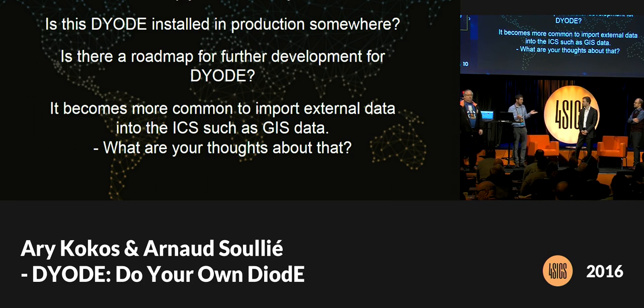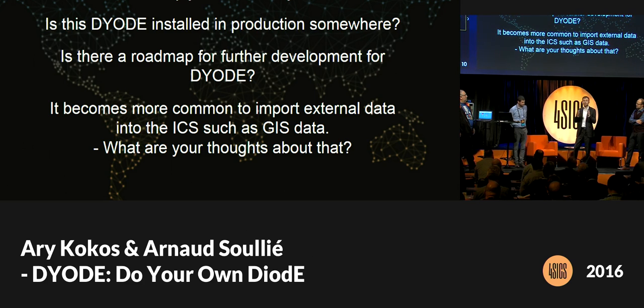And as Ari mentioned, most of the time on a big ICS network, you will end up with data diodes in both directions. So you also have to make sure that the way your network is segmented means that the data diodes are actually useful. Because if you just put one on this side and the other on the other side, then the security improvement is not that big. But usually what you do is manage this with what are called trusted converters. For instance, if you import CSV files with a specific format, like GPS coordinates, it's quite easy to write software that checks that only this information goes inside and no active code.